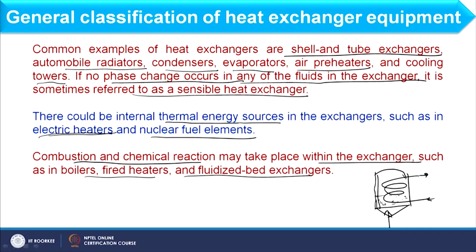Air, when it comes in contact with the coal, does two works. First, it fluidizes the bed, and second, it helps in combustion of the coal, because that will occur only in the presence of air. So, when this combustion occurs and the coal particles are fluidized, they cover the complete coiling in which water is flowing, and then water gets heated up inside this. So, that is basically a fluidized bed exchanger.